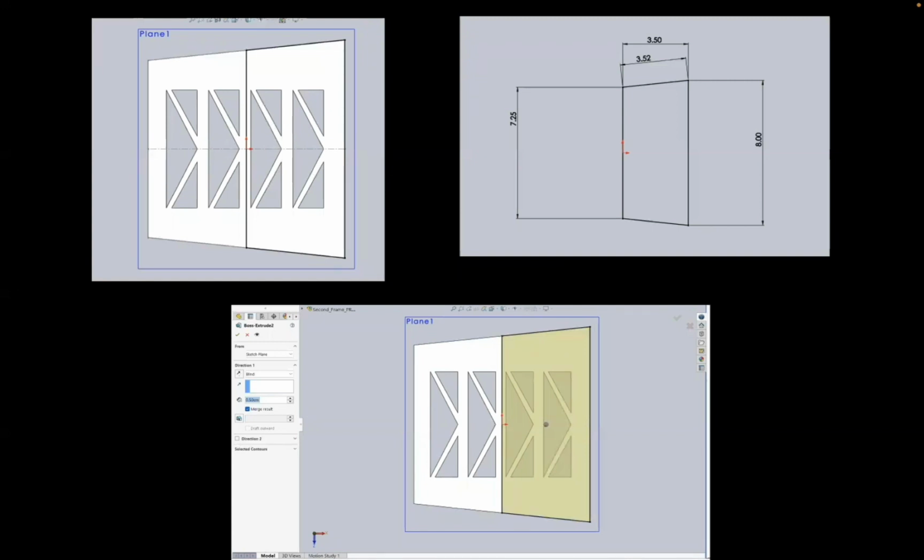The 3.5 cm slash on the two sides and the top and bottom lengths are created based on the dimensions of one of our group members', Eli's, hands. We extrude 0.5 centimeters up to create the base part, which provides small weight when carried on the hand. Also, the height is comfortable when the fingers carry the elastic cord.